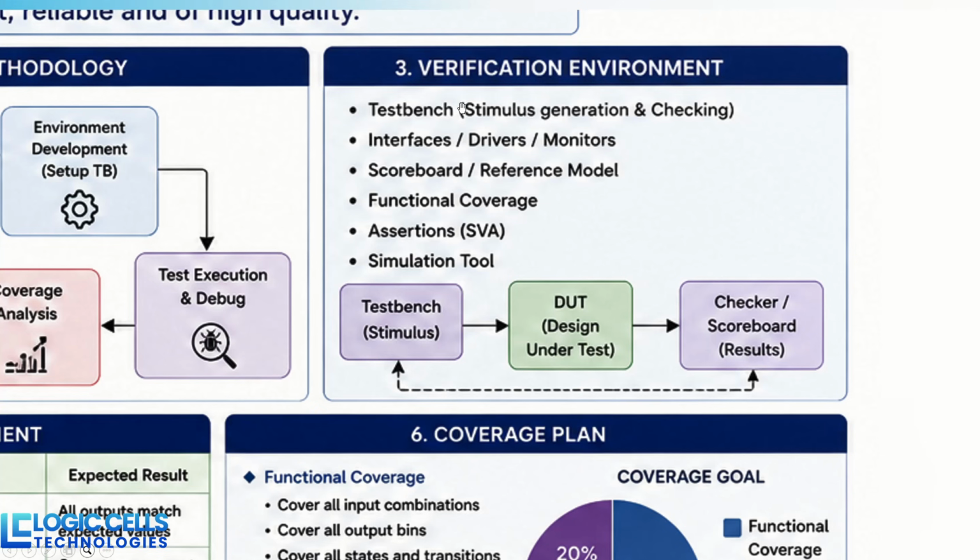And you can observe here, this is a verification environment. We will be having interface, drivers, monitors, scoreboard, and a reference model inside the scoreboard. This reference model itself gives you the expected or the actual value, and you will check it against the result of the DUT.